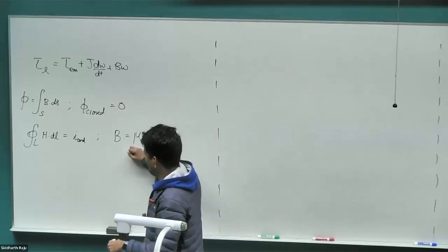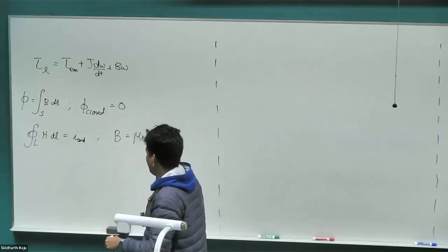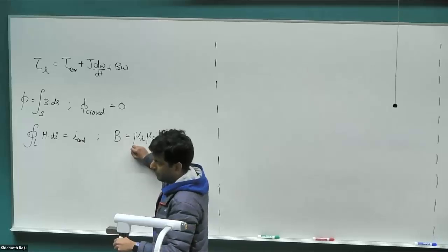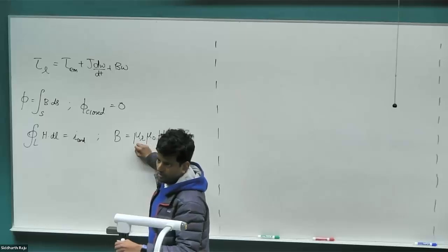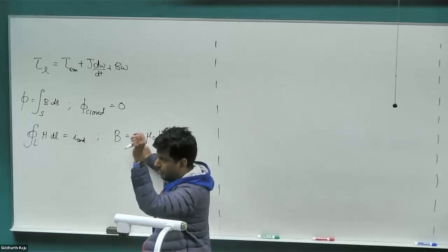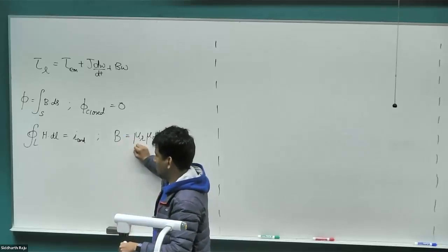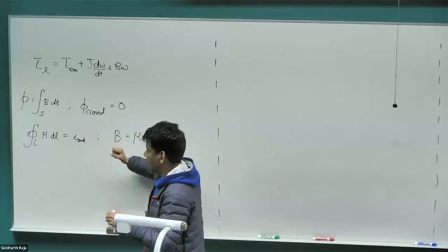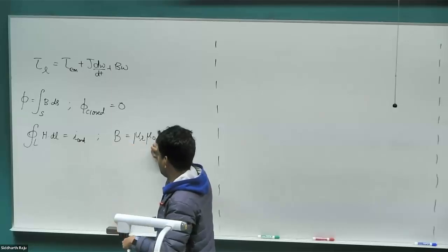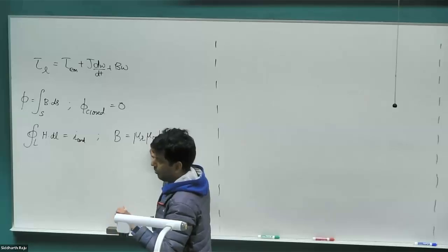Right. So this mu r changes depending on where you are on the BH curve. Except for the case of magnets, we won't think of cases where mu r is varying. Only in the case of a magnet do we look at the complex curve and try to figure out which point in the BH curve we are operating at. But otherwise, when we're looking at iron or at an air gap, mu r is always going to be assumed constant, with air as good as free space, and for iron, we are always going to assume that it's not going into saturation.